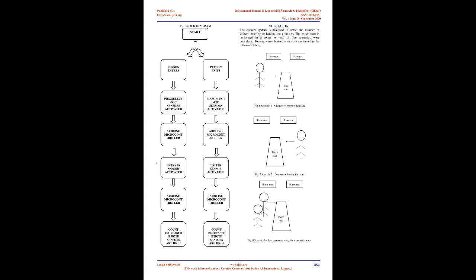B. Piezoelectric sensor. The piezoelectric sensor has the ability to convert mechanical stress to electrical energy, an AC output. The principle involved is the piezoelectric effect. It is a reversible effect, meaning if electric energy is provided, mechanical stress is induced. Common materials used in piezoelectric sensors are quartz and Rochelle salt. Synthetic materials including zinc oxide and gallium arsenide are also used. The sensor has 2 terminals, namely positive and negative. The positive terminal is connected to one of the analog pins of the Arduino and the negative terminal is connected to ground. By pressing the sensor, the mechanical energy produced is converted to electrical energy. Fig. 2 Piezoelectric sensor.